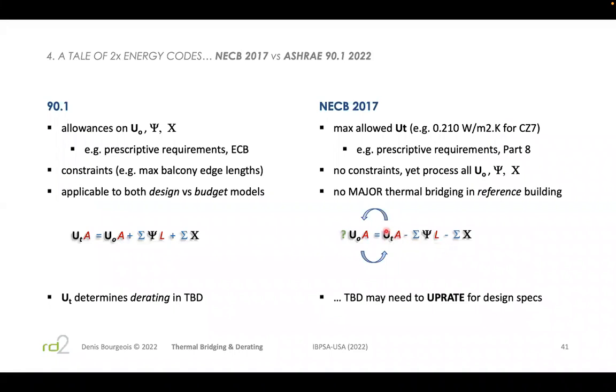So if I have a 0.21 value here, and I'm subtracting thermal bridging, it's not complicated to understand that if this is equal to 0.21 as a sum, I have a U0 of 0, which means infinite insulation. That's not going to happen. If that number is superior to 0.21, then it's physically impossible to achieve a compliance of 0.21 or R27.